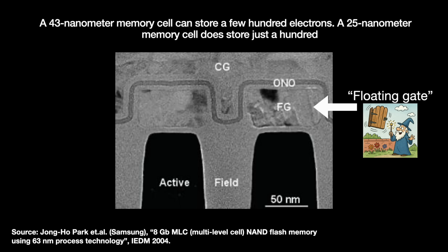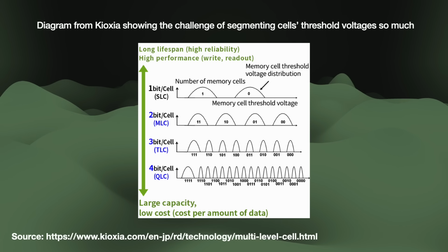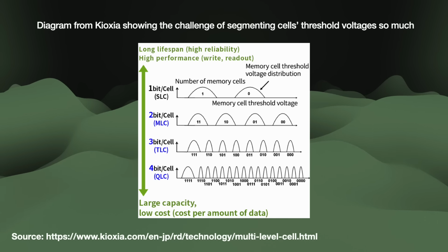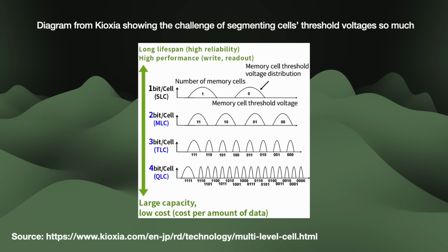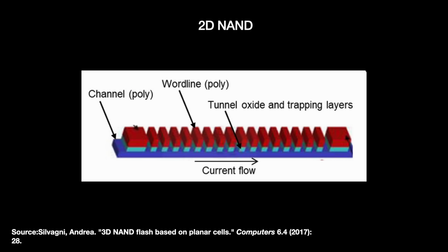The multi-level cells have this even worse. Their 100 electrons have to be divided amongst the cell's multiple bit levels. Each division is now only a third or half the previous size. This not only makes it more likely that degradation via leakage occurs sooner, but also lowers the signal-to-noise ratio. Now losing just 10 electrons materially affects the cell's contents.